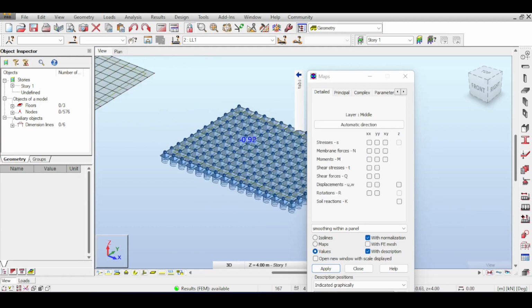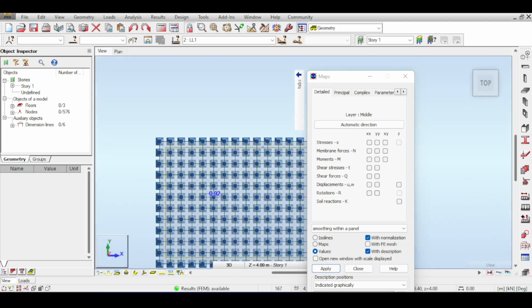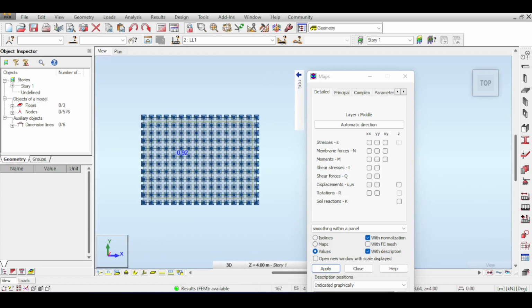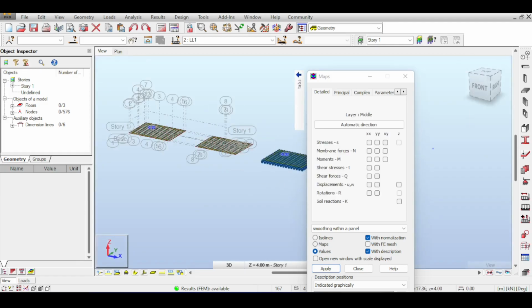Just recap. I just defined some springs. Of course, the spring stiffness was the earth stiffness multiplied by the tributary area of the spring, which means that I had to define 3 springs, one for the internal nodes, one for the edge nodes, and one for the corner nodes, and it worked out fine. Now, I think this will not work, right? It will not work. Yeah, of course it doesn't. Yes, okay.